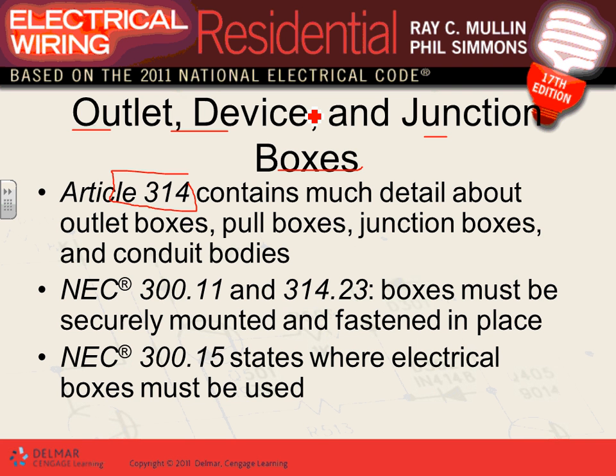They used to do that. What's wrong with splicing in the air? Why do we have boxes? The NEC code book requires you guys, when you deal with electrical power, to use boxes and conduits and cables at all times. Every time you splice, you have to splice in a box. The idea behind splicing in a box is eliminating the possibility of fire generated from any arc or fault in the connection. The weakest link in any power system is the connection.